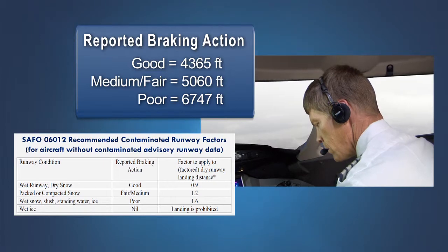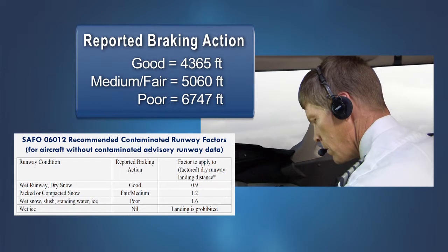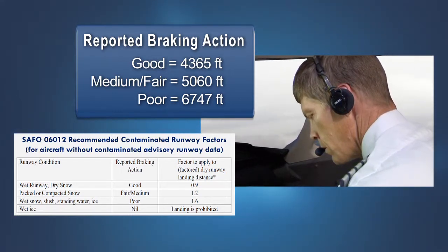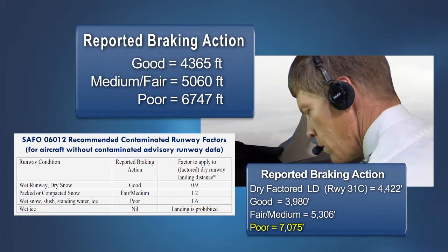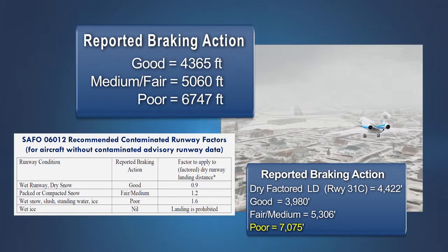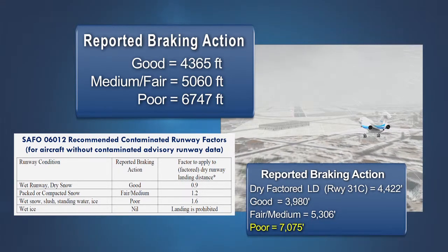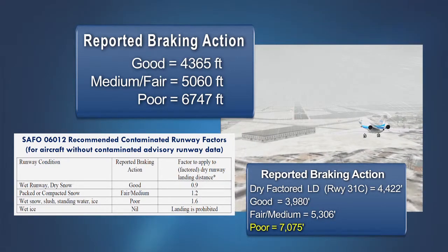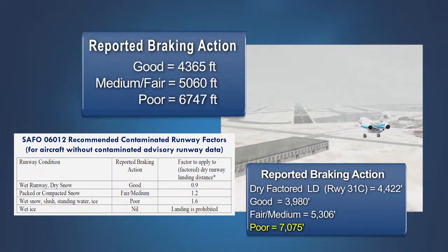In some cases, contradictory information concerning runway conditions or braking action reports may force the flight crews to apply their best judgment about which information is likely to be most accurate. The receipt of new or updated information on runway conditions may result in the reevaluation of a previous decision to land. In a case where uncertainty of landing distance remains, it may be appropriate for the pilot monitoring to quickly reference the QRH or tab data, or in other cases, the prudent use of a go-around and a holding pattern at a safe altitude to reevaluate the decision to land or divert may be the best decision.